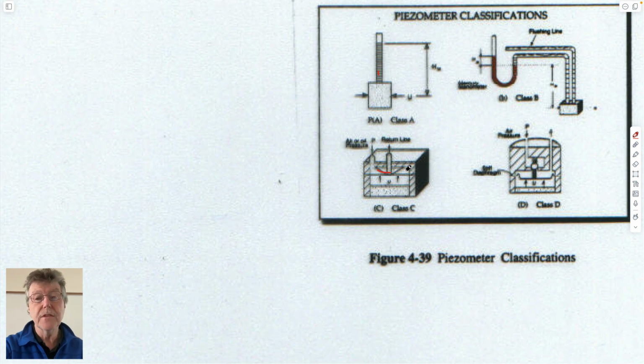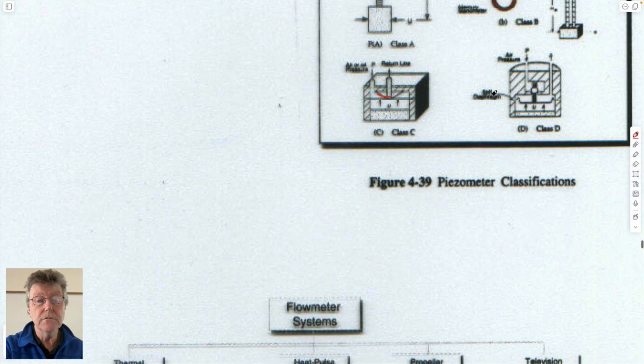You could run a permeability test in this piezometer. You can water sample from it for quality. You can also get water levels from this rudimentary sampler. You can't get water quality samples from any of these other three methods.